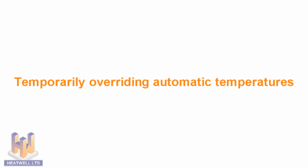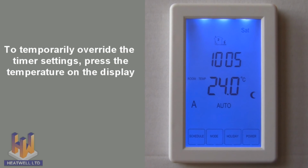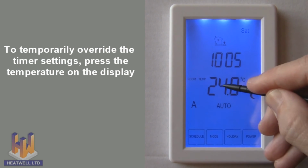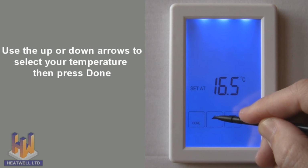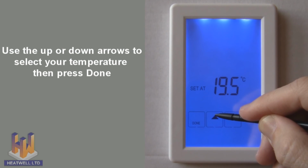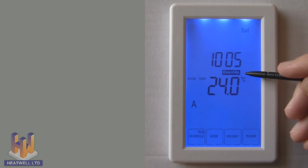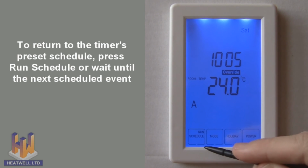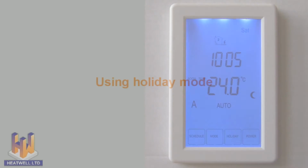To go back to the automatic schedule, press the Mode button. Temporarily overriding the automatic temperatures. If you wish to temporarily force the unit to warm up or cool down at any given moment, simply press the temperature shown on the display. Then choose your desired new temperature and press Done. The override symbol will display and the unit will stay this way until you either press the Run Schedule button or until the next scheduled switch on or switch off event occurs in the unit's timer.